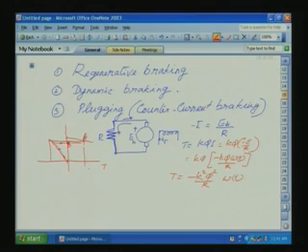Now, another way of doing it is plugging, which is seldom used. See, plugging means the polarity of the motor is suddenly reversed. If the armature voltage is suddenly reversed, heavy reverse current will flow and the system will stop immediately, but that is seldom used. Maybe for low speed, when we quickly want to make it 0, we can momentarily reverse the voltage, so that with the low back EMF and this applied voltage, the sudden current is still well within the maximum rated current.